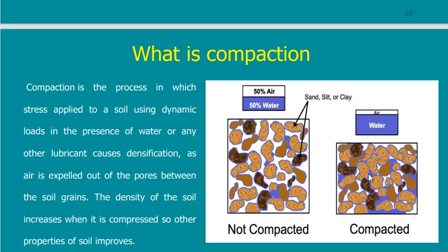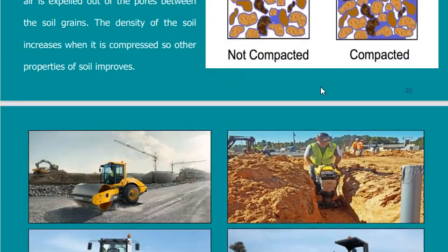In the consolidation case, we have to wait for the water. We are under its will. We cannot just push as much as we need. No. Whether you push or you don't push, water will not be expelled except depending on the permeability of the soil. So this is compaction.